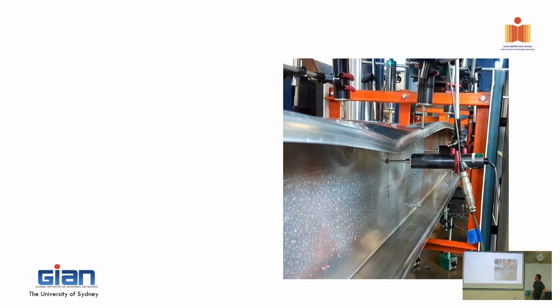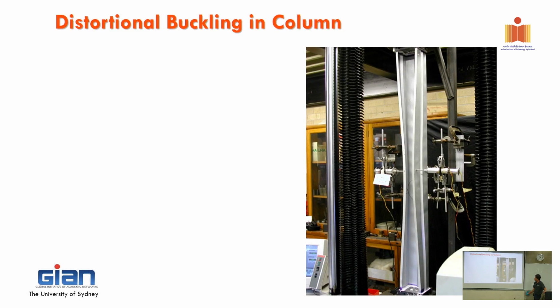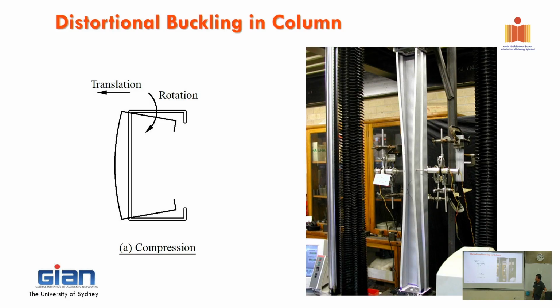Can you go to the previous slide? So this information, can it be the other way? Yeah, it can open now. Both are possible with similar conditions? Yes, right. It's so sensitive to imperfection. The channel section is never perfect. Normally it opens a little bit out or in, and the imperfection will guide whether it comes in or out. So it can be either in or out, but they will give you exactly the same critical load.